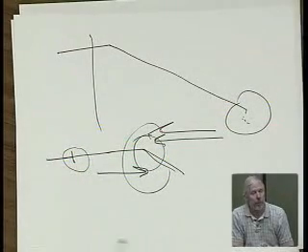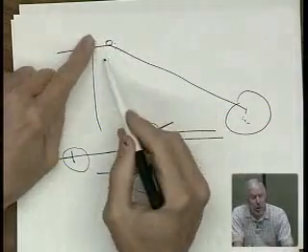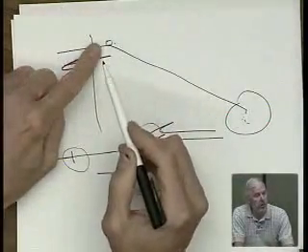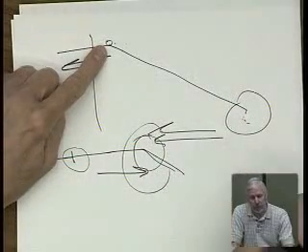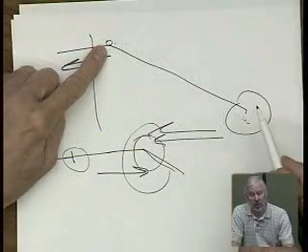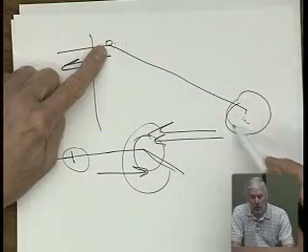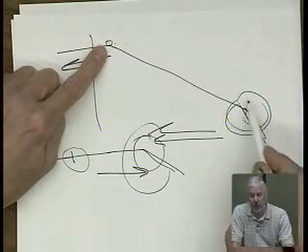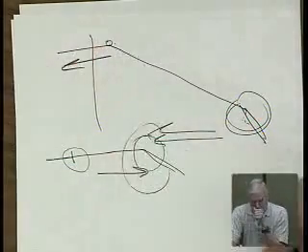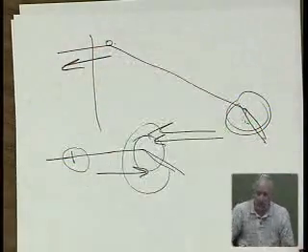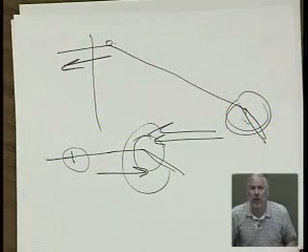It's going to be different when we do the stability problem, because I say we will take one pole and run it to a very low frequency and use that to kill the gain so that we can make the circuit stable. And so we will then have a whole bunch of poles at the second spot, or near the second place. But the lowest frequency pole we will make artificially low. Okay?